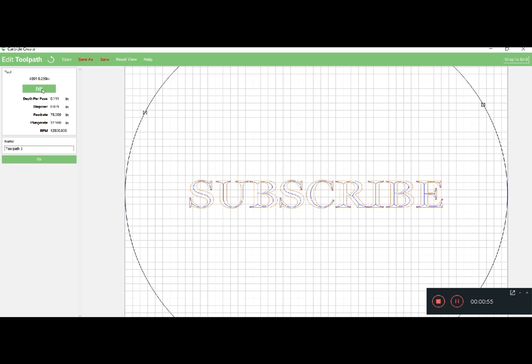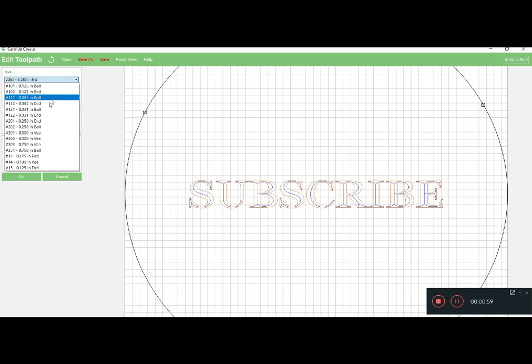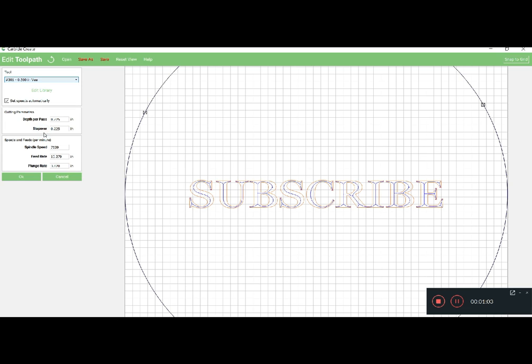So what we're going to do is edit this, and we're going to come over here and use a 301, which I believe is a 90 degree. And the speed rate here, 15. We'll bump this up to 25 because, again, we can manually change that. So we'll go 25. Plunge rate, we'll go 15.